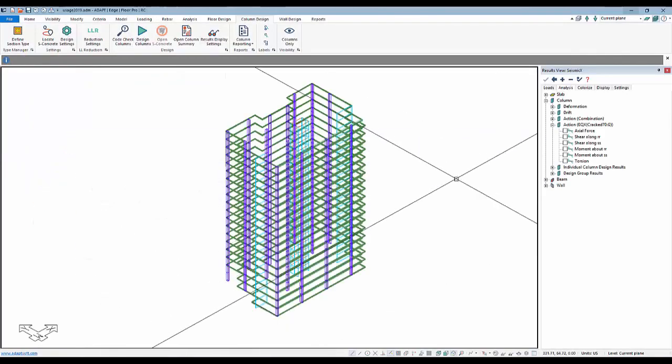The program does store reactions for every global run made. So if I ran the program for cracked 70, cracked 50, cracked 25, you would be able to access those reactions either graphically or through application of a single level rerun where you could then apply those reactions from any solved usage case.